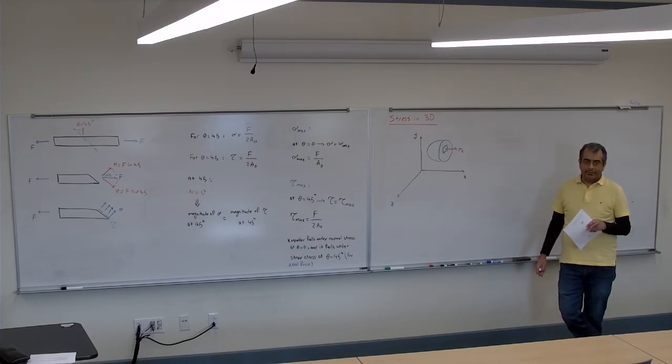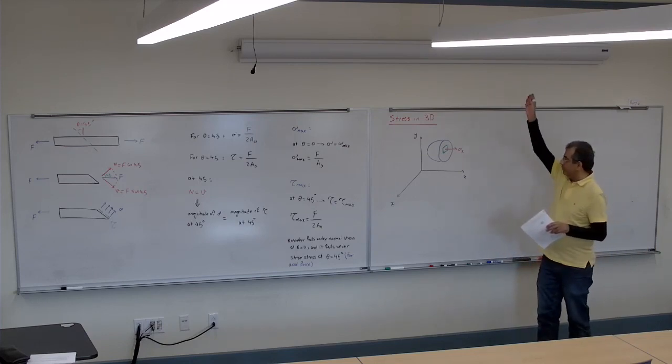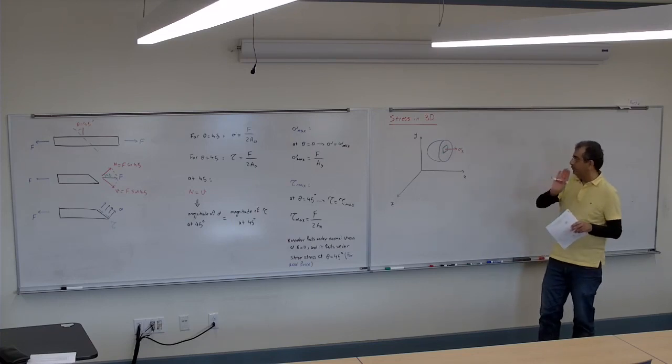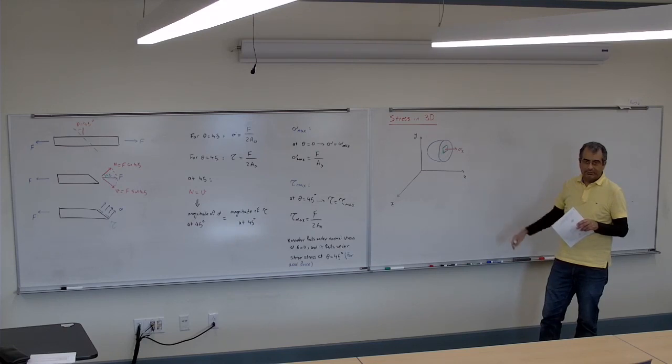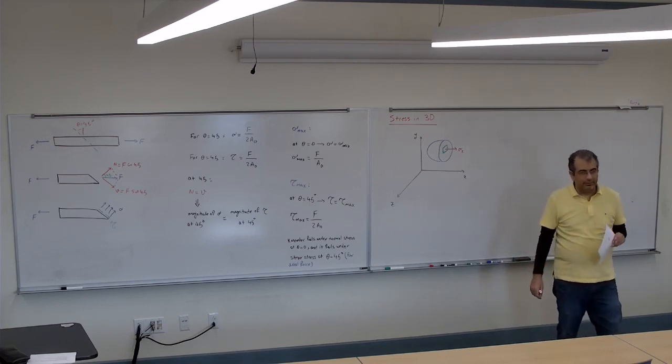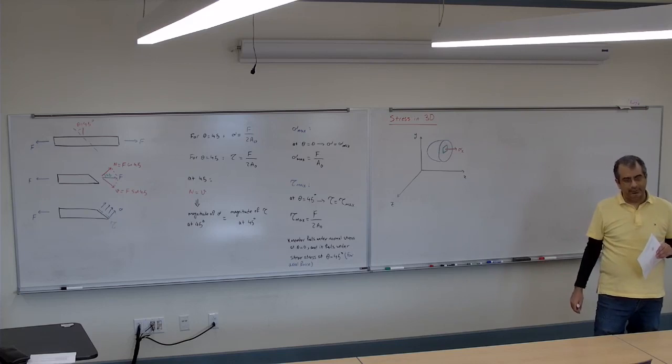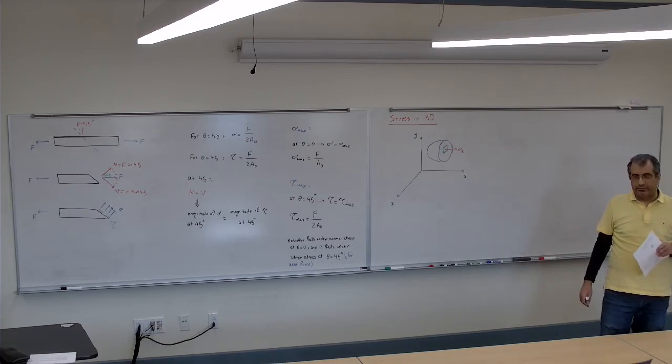So I can cut it from top to bottom, or from left to right. Can I cut it any other way? Any way that's parallel, you can, but it's just maybe flip the arrows. If you cut down, it's the same thing as cutting up. As long as it's parallel to that front surface, it's going to be a shear force.